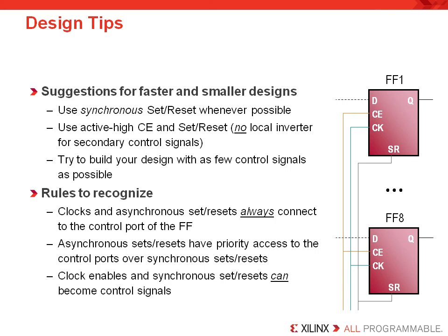And then some other rules to recognize: clocks and asynchronous sets and resets always connect to the control port of the flip-flop. Asynchronous sets and resets will have priority access to the control ports over synchronous sets and resets. And finally, clock enables and synchronous sets and resets can become control signals to your system.